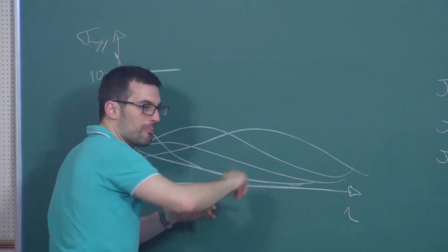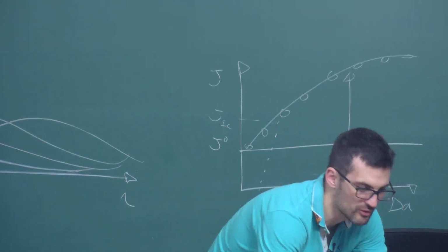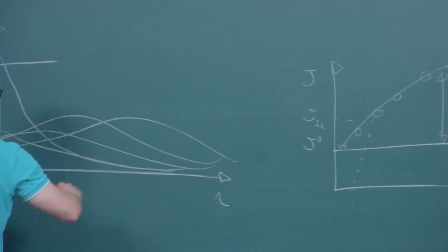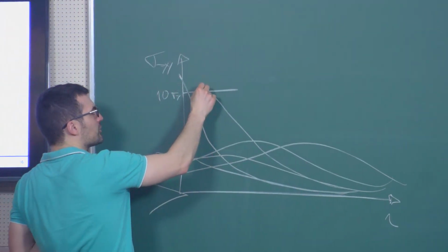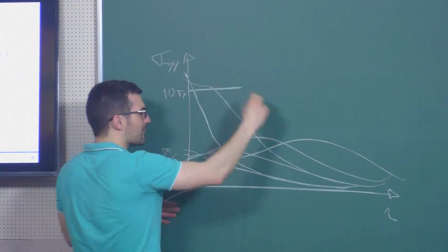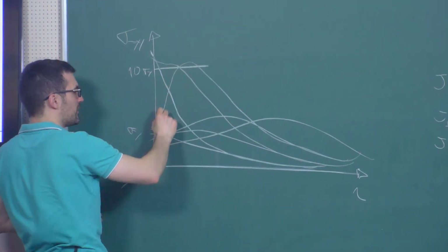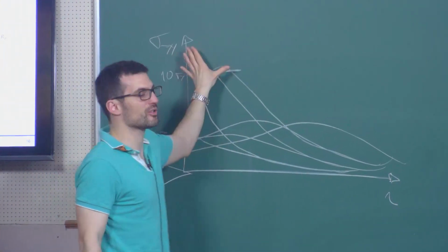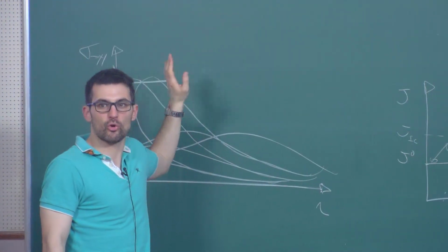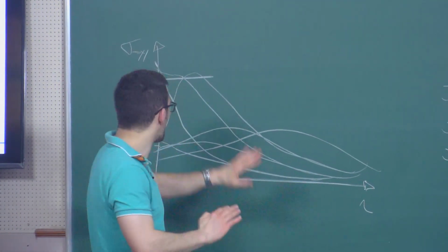And then, how big the elevation will be will depend on L divided by R0. So it depends on your length scale and so on. But for any material, you start loading this thing. And then normally with metals, you get something like this. Sometimes eventually with gradient plasticity, when you do large strains, you get a drop eventually. So all of these things are high enough, but they are not high enough over a sufficiently long distance. So I need something else. I need microvoids to grow and coalesce. Otherwise, I cannot get failure.